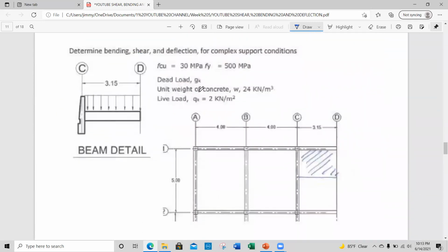So for example, we have here an extract of the floor plan. As part of our analysis, if there is a combination of structural steel and a concrete slab, then of course we have to take that into consideration. Let's say for a conservative analysis, we can just consider this area to be carried by this cantilever beam, with some load given, for example here with the concrete. For some considerations, you can have this 45 degrees, but just say we consider just this one.